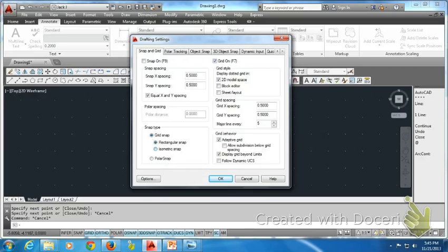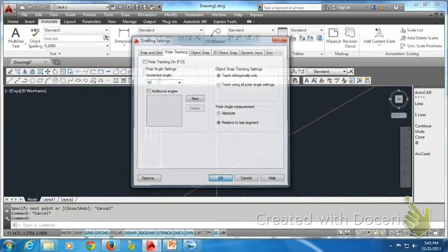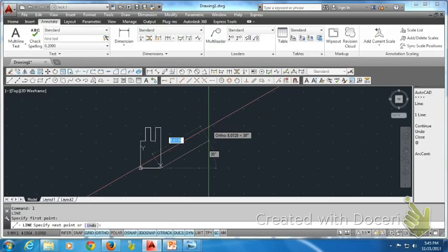You'll notice that on the isometric, I can control angles on the polar, the grid snap. We're going to use this. We can actually go to this angle if we wanted to change it to 45. Hit OK. You notice that now my cursor has changed from a 30 to a 45. So let's go L, enter. Let's put an edge.